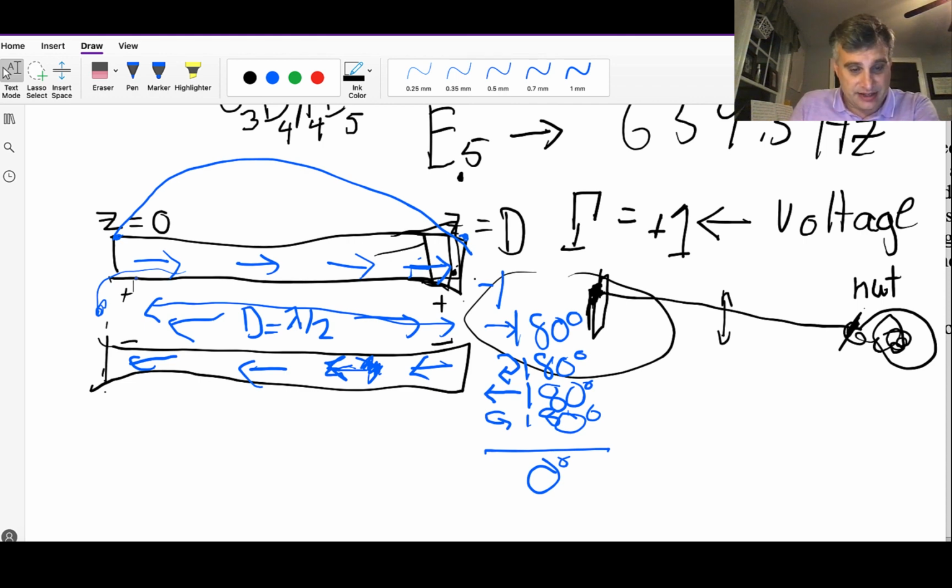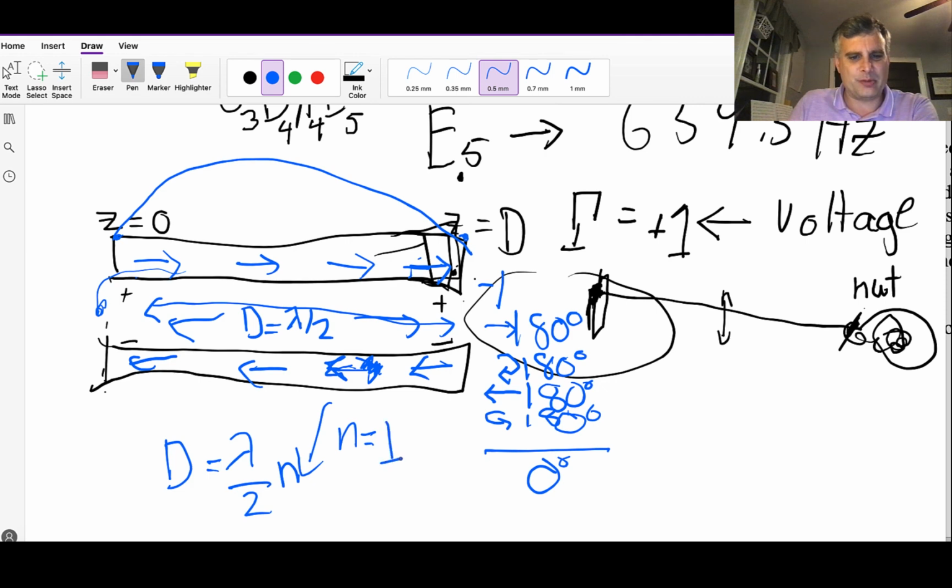If I change that length, I make it a little bit greater than one wavelength or a little bit less than one wavelength, I get complete destructive interference when I have successive reflections again and again and again through the structure. So only this resonant lambda over 2 times some sort of integer length can support this type of wave. And the fundamental, of course, occurs in both acoustics and electromagnetics when n is equal to 1. That's the dominant mode that's going to form here.